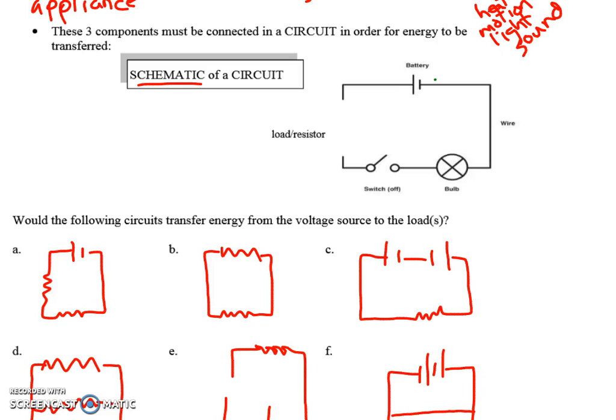So let's start with the voltage source. A voltage source is represented with two parallel lines, where one line is longer than the other. The longer line is always the positive side, and the shorter line is the negative side. This is a cell technically, and if we want a battery, we just put a bunch of them together. So sometimes you see multiple sets of these parallel lines, which just represents a bunch of cells.